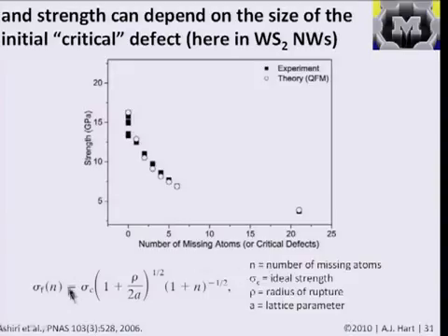And they say that sigma c is an experimentally determined value for the ideal strength of the material, and you can think of this kind of like a macroscopic crack mechanism. Remember, in stress concentration, we had the radius of a crack a, and here they're calling rho the radius of rupture, and a is another characteristic length that corresponds to the lattice parameter, or the size of the rupture relative to the lattice parameter.